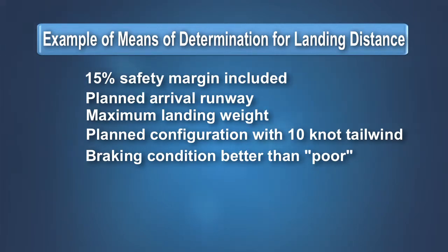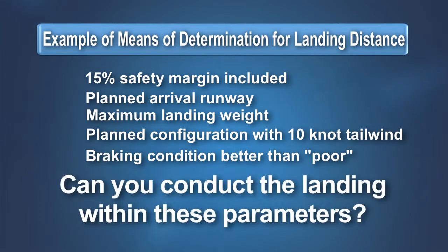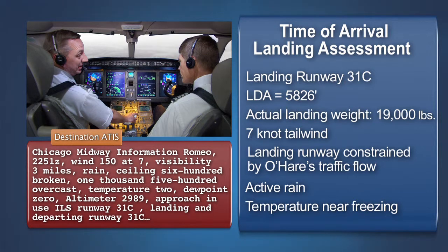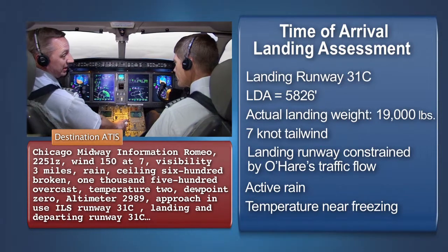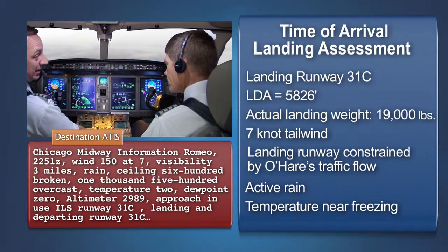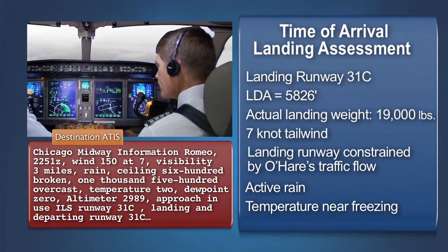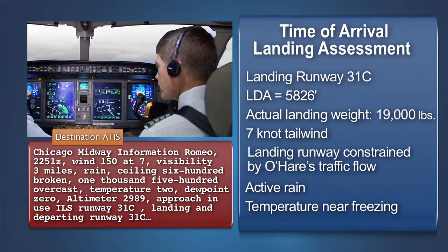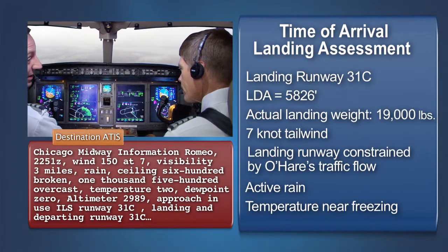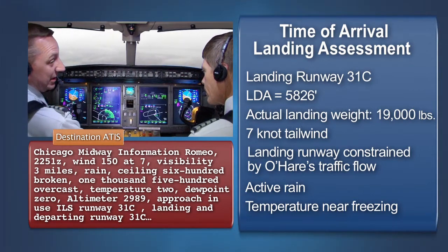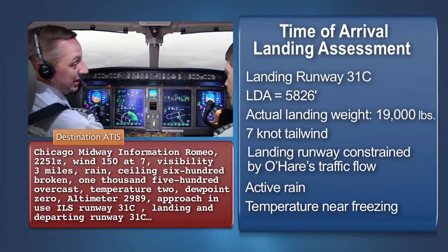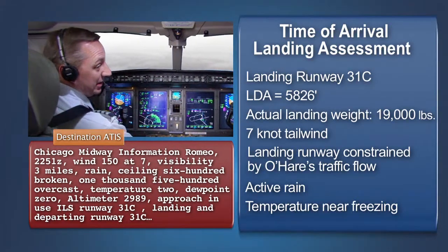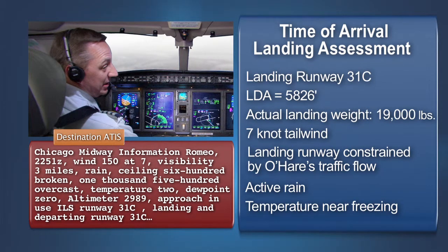Your assessment at the time of landing may be as simple as verifying that the landing would be conducted within those parameters. This landing distance assessment should be accomplished as close to the time of arrival as practical, taking into account workload considerations during critical phases of flight and using the most up-to-date information available at the time. Pilots should also look beyond the current conditions and plan for the worst-case conditions. Additionally, operators should use the most adverse reliable braking action report if available, or the most adverse expected conditions for the runway, or portion of the runway that will be used for landing when determining the landing performance assessment.